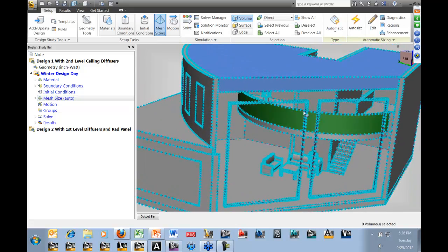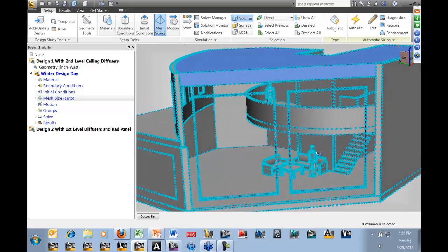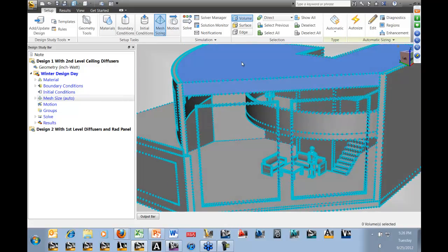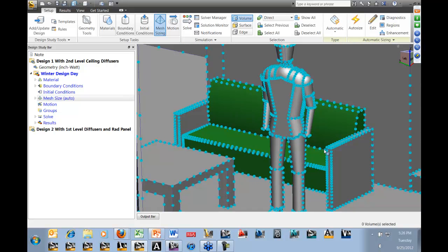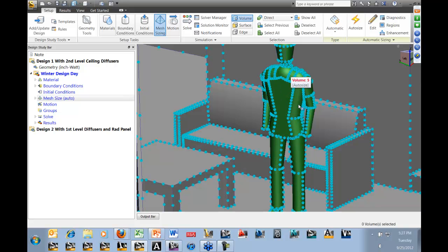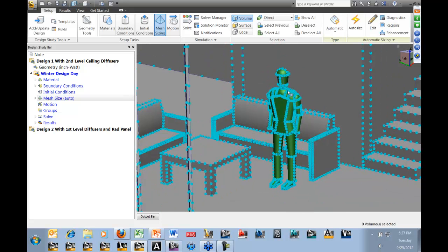And so meshing has historically been just very difficult and very painful in a lot of the older traditional simulation tools. Within Simulation CFD, it's very different. So we're taking that native Revit geometry, which is a benefit already, because we know we're creating really solid, high integrity geometry in Revit and pulling that in. But what Simulation CFD does is it looks at two things: edge length and curvature.